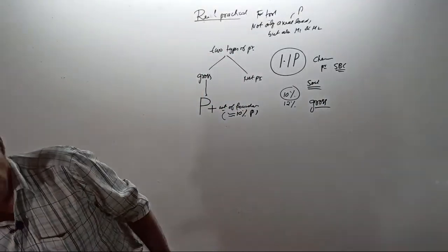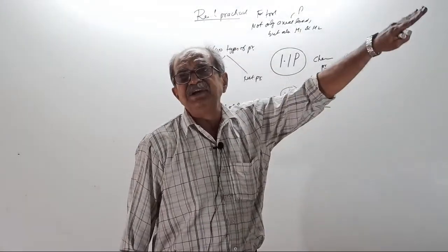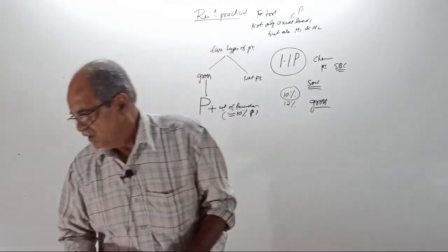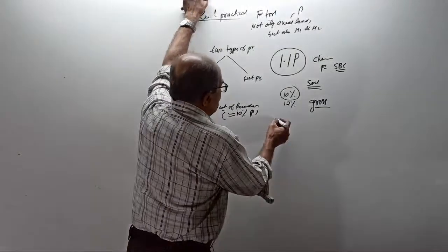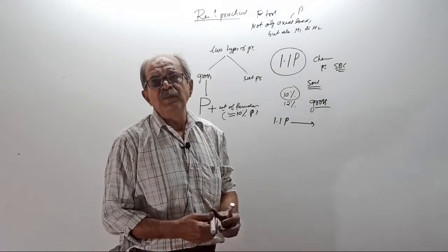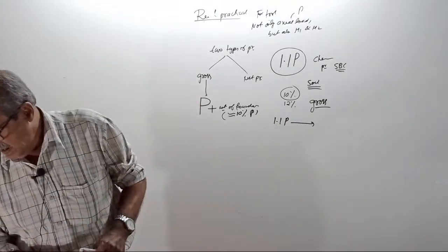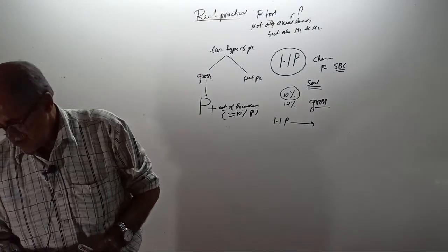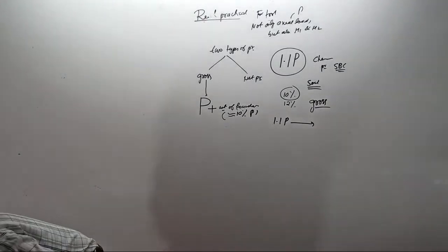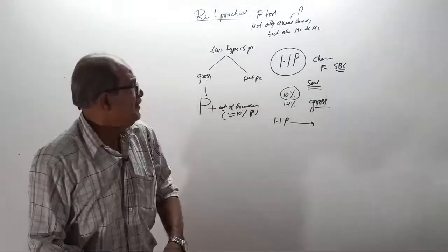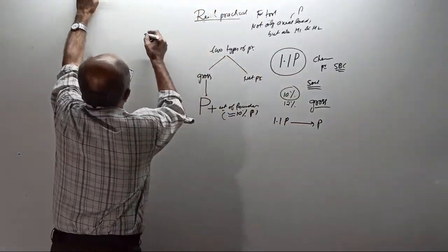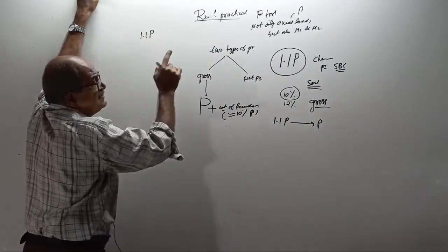I told you, when you consider bending moment, shear force, etc. for the footing slab, at that time net pressure, that is, not 1.1 P, only what? Tell me. Only P. Remember, therefore in the formula, if you write 1.1 P, it means gross pressure.